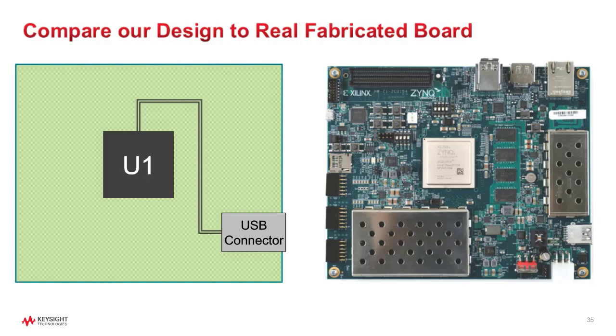You don't really need AMI models for the Rx and TX for the channel response. But if you want to look at how the channel will behave in a realistic situation, that is a great place to be. You have your IBIS model, input buffer specification information, and the AMI model, the interface for algorithm modeling. That'll be a great thing to have: on the left you have a TX AMI, on the right you have your RX AMI, in the middle you have your channel. That is just a real great simulation to measurement workflow. That's as close as you can get.